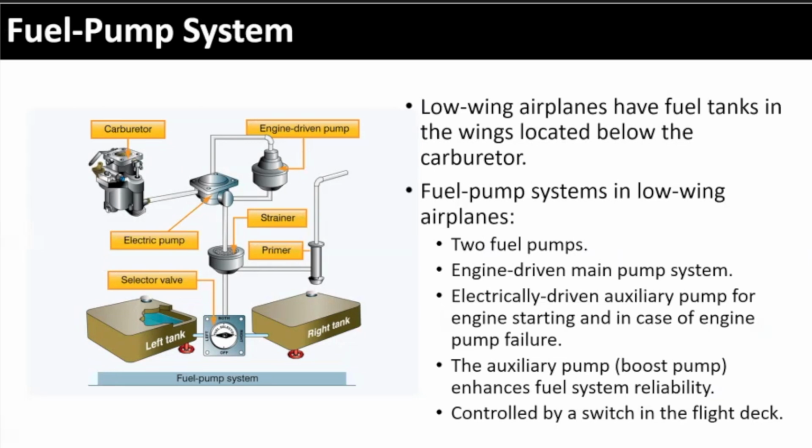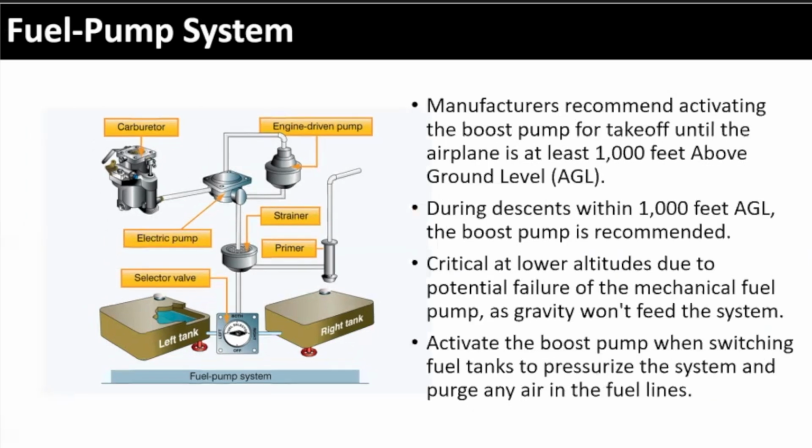Okay. Any questions? All good stuff? All right, the top line there talks about recommended actions for activating the auxiliary fuel pump. There's different phases of flight. What happens if you are in a takeoff or landing phase? What happens if you're on short final to the runway and that engine-driven fuel pump dies on you? If you don't have the electric on, what's going to happen? You may end up coming in short of that runway.